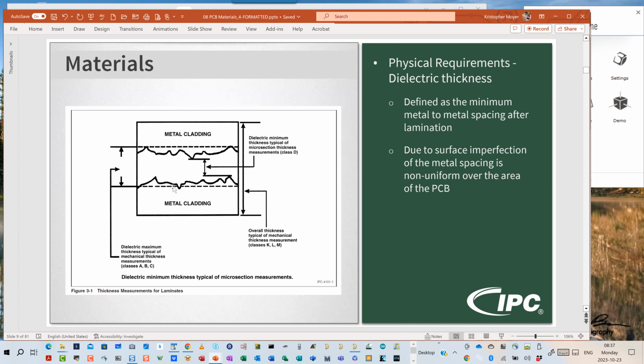And when they harden or cure, that hardened resin now has effectively a hook and eye, or a mechanical interference, to the structure of the other material. This is how all adhesive bonding works, no matter what type it is.